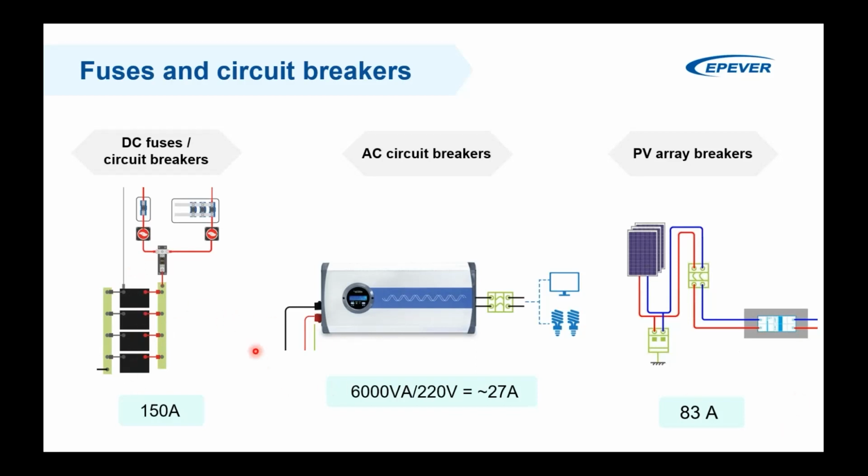So a DC circuit normally contains a main battery fuse, which is here, after which it branches to the individual users. Here I've applied, just for example, a fuse for the inverter itself and a fuse for charging itself. What is the advantage of this? Well, if there is a fault in the inverter, for example, this fuse will blow first, and this other fuse will survive.